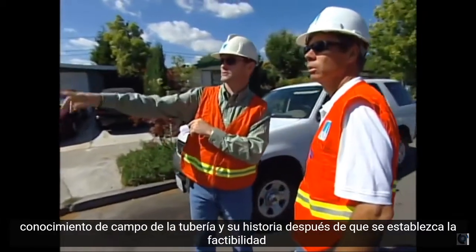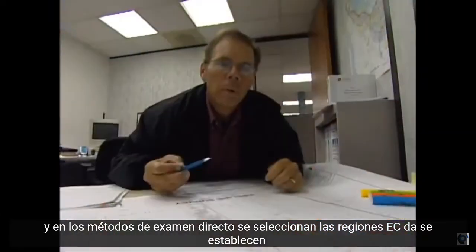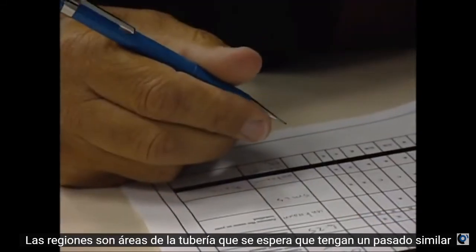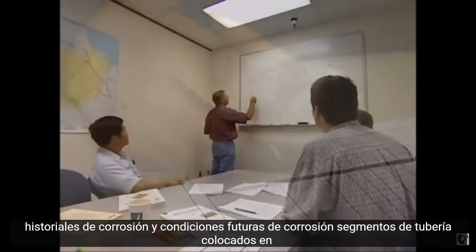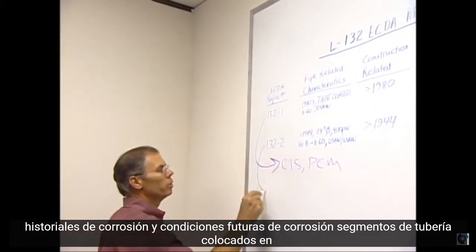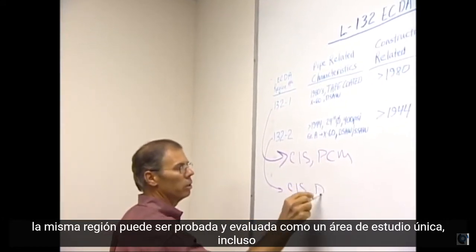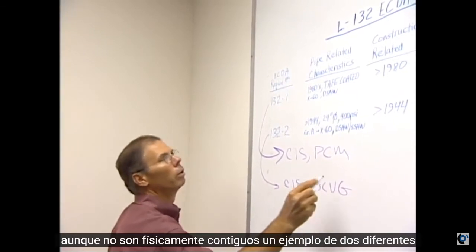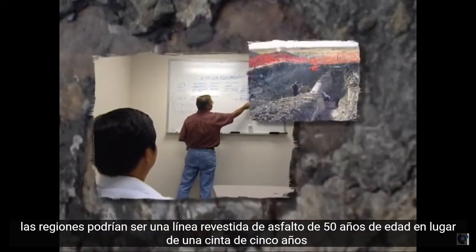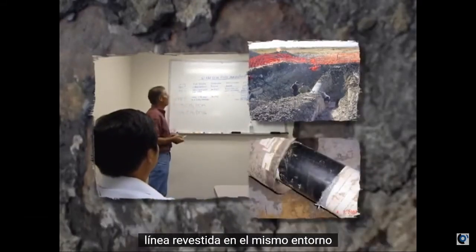After feasibility is established and indirect examination methods are selected, ECDA regions are established. Regions are areas of the pipeline that are expected to have similar past corrosion histories and future corrosion conditions. Pipeline segments put into the same region can be tested and evaluated as a single study area, even though they are not physically contiguous. An example of 2 different regions could be a 50-year-old asphalt-coated line versus a 5-year-old tape-coated line in the same environment.